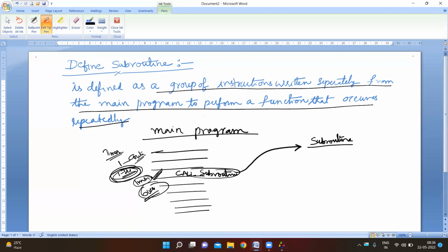To increase the minute counter by 1, we have to execute this 1 second delay 60 times in case of a clock program. So writing 60 copies of the 1 second delay program in the main program, the program length will become very vast, and the program memory size also increases very high.